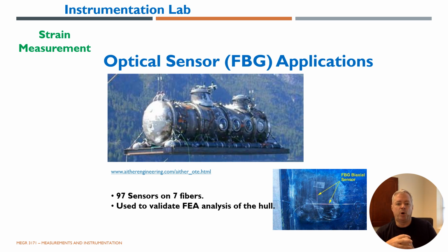And really the purpose in this particular test was to correlate the FEA analysis with real-life submersion. And then you can use that to create models, to improve your models, to do more complex FEA because you have better boundary conditions, better actual conditions. So it's a tool to improve design in this particular application.